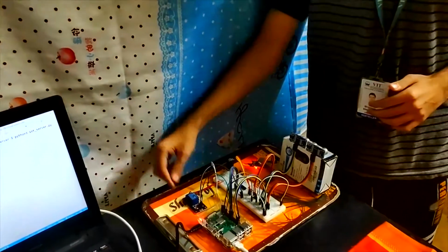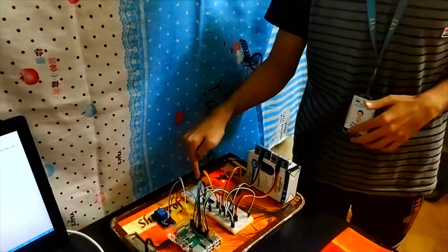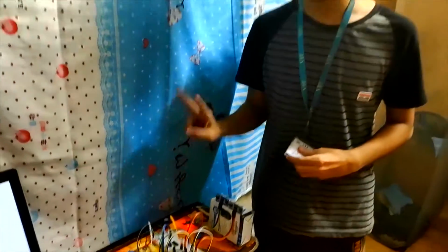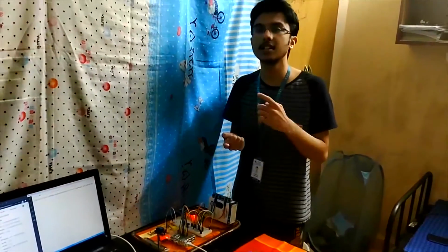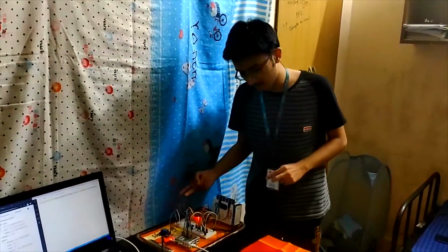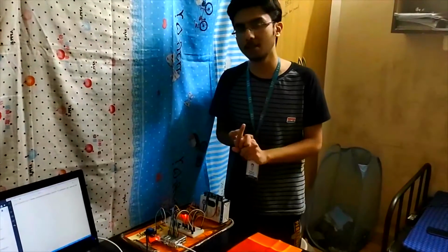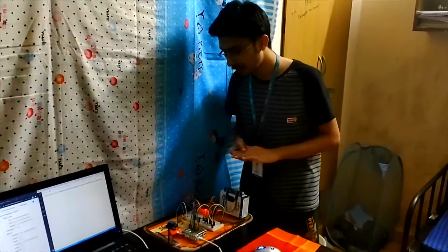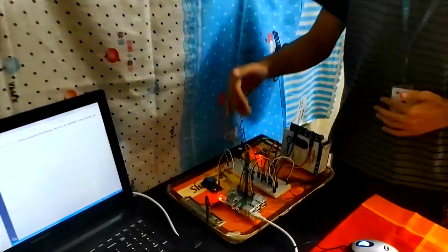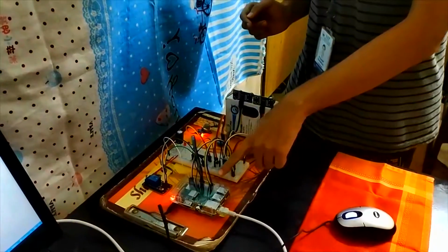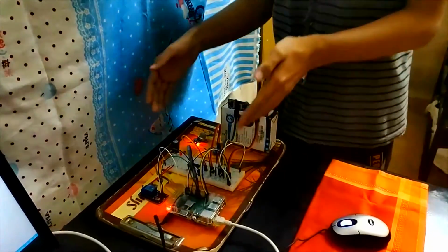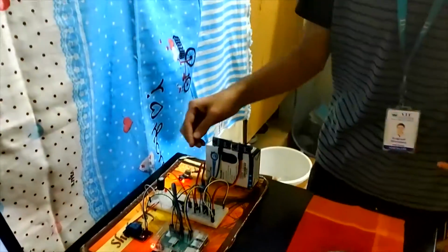The relay module is controlling the operation of this LED, which in our circuit is simulating two circuits. Sometimes it is behaving as the geyser, and some other times it is behaving as a bulb that will be connected in an actual circuit. The Raspberry Pi controls all these components together via the use of GPIO pins that are connected to the required places using some jumper wires.